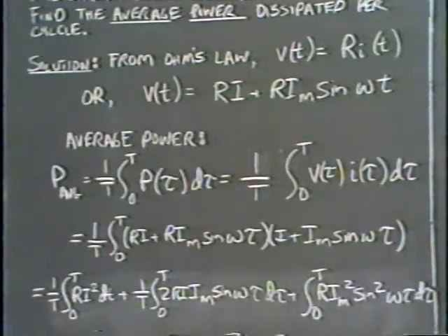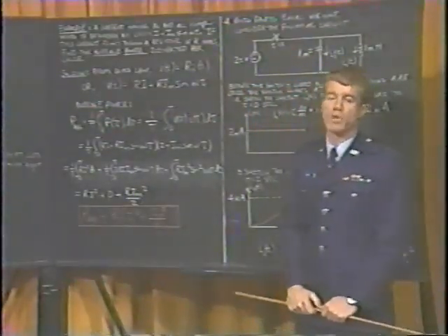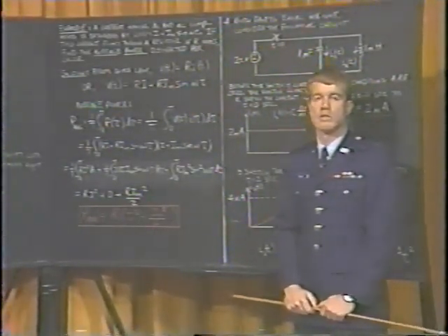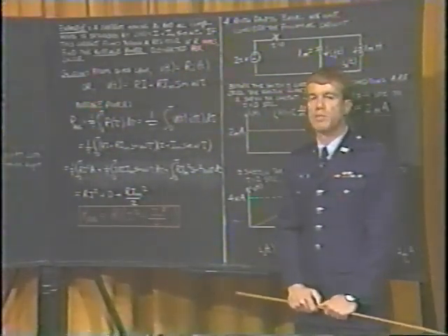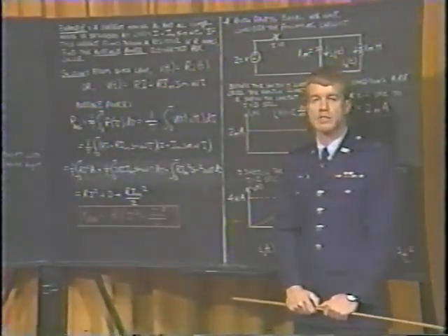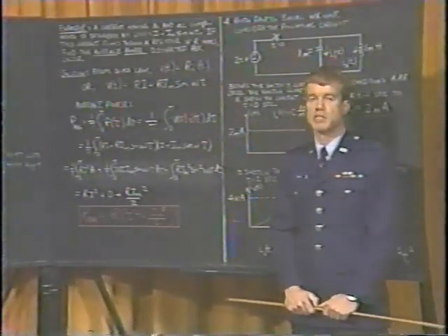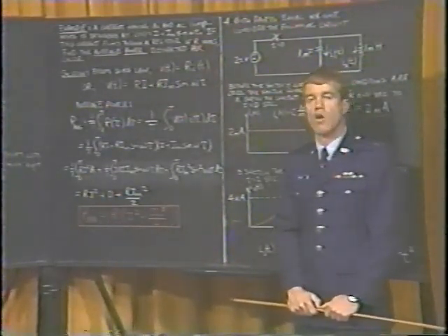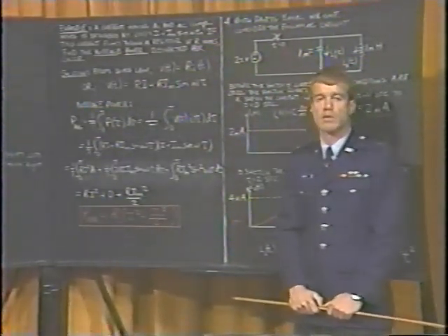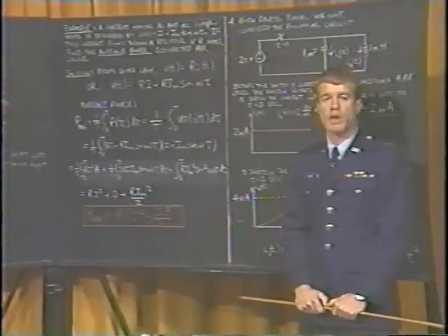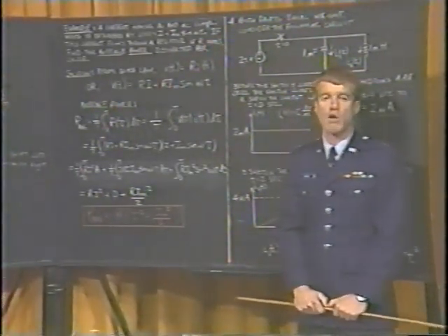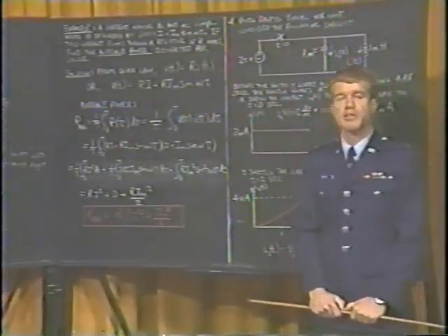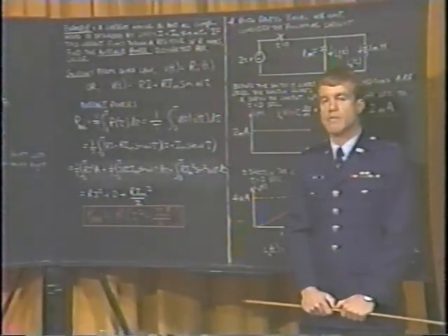Now, one of our basic electrical variables was that of power. We saw that we could define that in terms of the product of voltage and current. But unfortunately, if we just multiply voltage and current together in this case, we will get what is termed instantaneous power. And the problem asked us to average that over one cycle of the power. Because voltage and current both have a period, the instantaneous power will also have the same period.